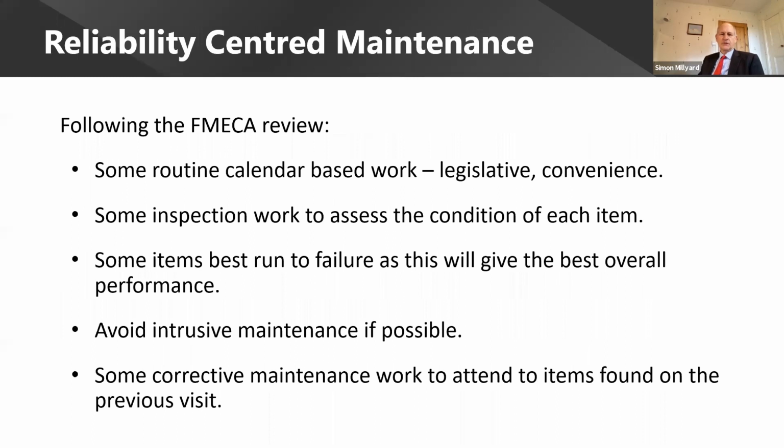So then you've done your failure mode effects and criticality analysis, and you're going to come up with a mixture. You're going to have some routine calendar work based around the phases of the sun and the moon. Why? Well, sometimes you're driven to it. For example, if you have a lighthouse that is occupied, you may have fire extinguishers on board or fire detection equipment, and that may have a legislative requirement to be tested, inspected annually. Therefore, you have to do that. Others, it might be convenience. You're going there and you have an annual budget cycle, so annually seems to be convenient.